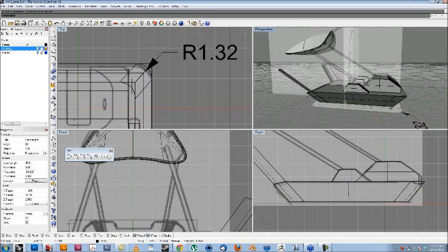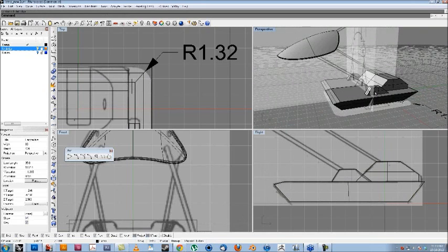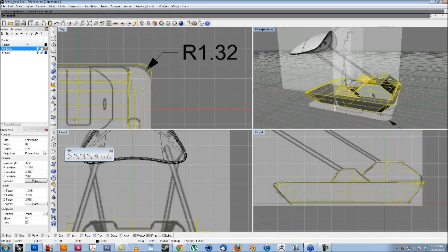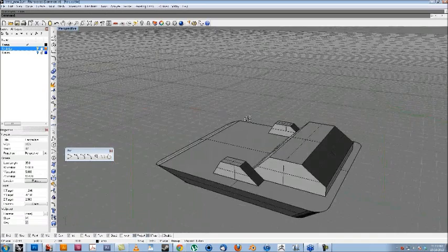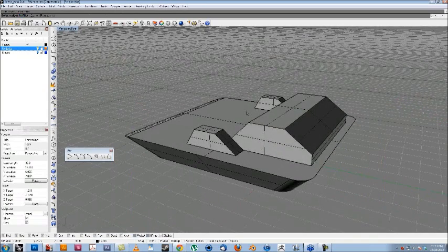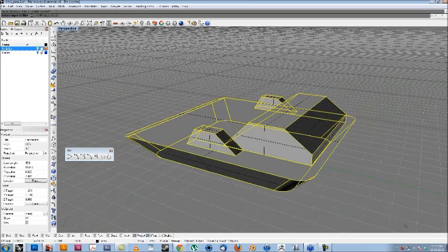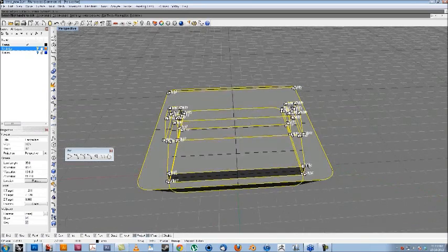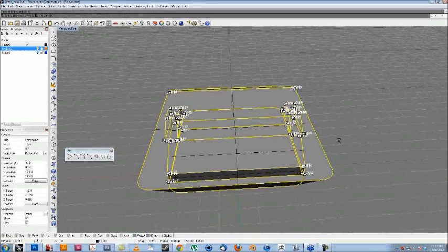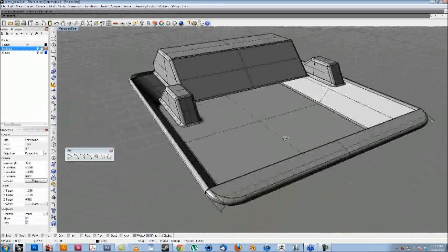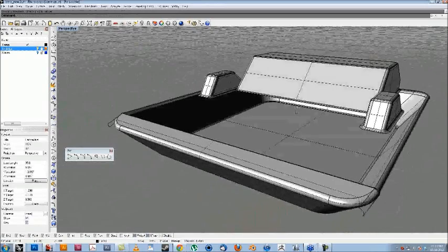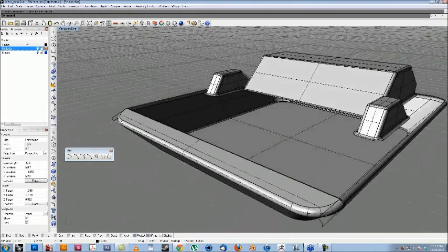And that kind of broke, so we might have to mess with that a little bit. So I'll take it to just a 1 because I'm pretty sure last time I did this, that's what happened. Yep. Okay. So now I'm going to invert everything and hide it, and then put some fillets back into this. So fillet edge and 0.12 I believe worked. And this is the other really cool thing about the fillet command: you get a really nice result, as you can see, except for the face had gone off here. Let's see what the issue is.